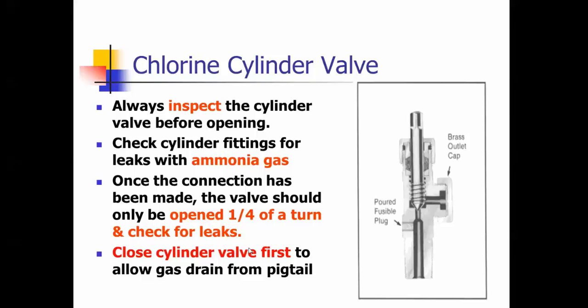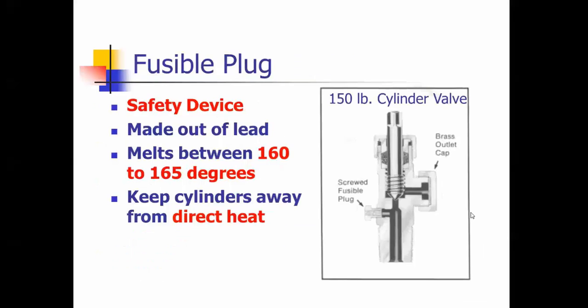That is a test question that a lot of people miss. You don't close it at the manifold. You always close it at the cylinder because that's the source, and then it allows the gas in the pigtails to drain off the lines.